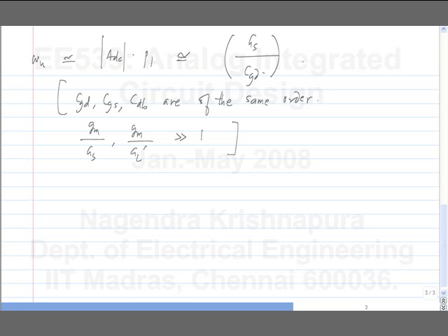Yeah, that's correct. So what was it you said earlier? At this frequency, the feedback fraction is 1. That doesn't directly say that that's the unity gain frequency. In fact, if you look at the feedback fraction, that's 1 over square root of 2, right?